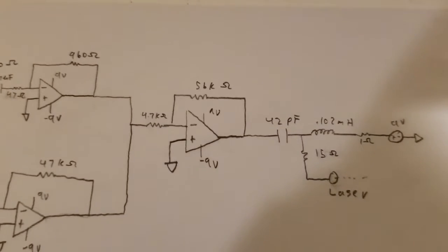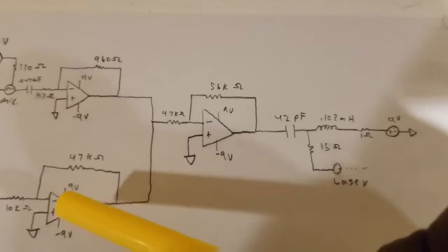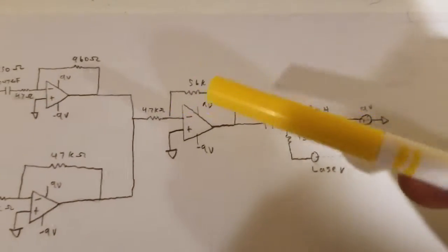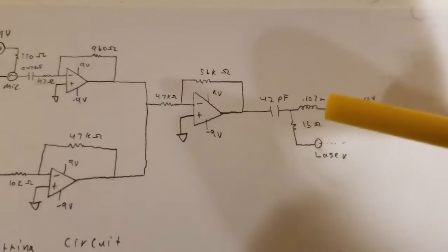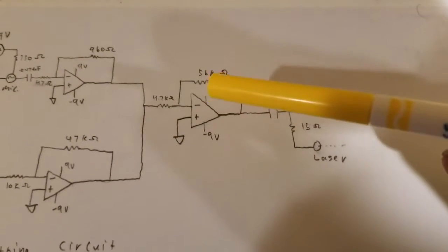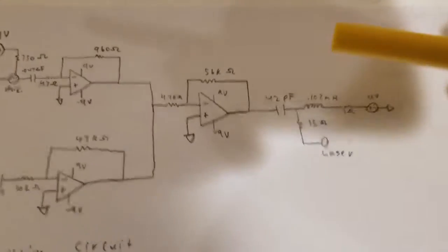And in the next op amp, we have the signals from the microphone, which is on top, and the phone being added together, summed, which is why this is called a summing op amp, in this op amp here, which is once again another non-inverting op amp, where we have the feedback resistor on top and then the other resistor here to create a gain to make it louder.